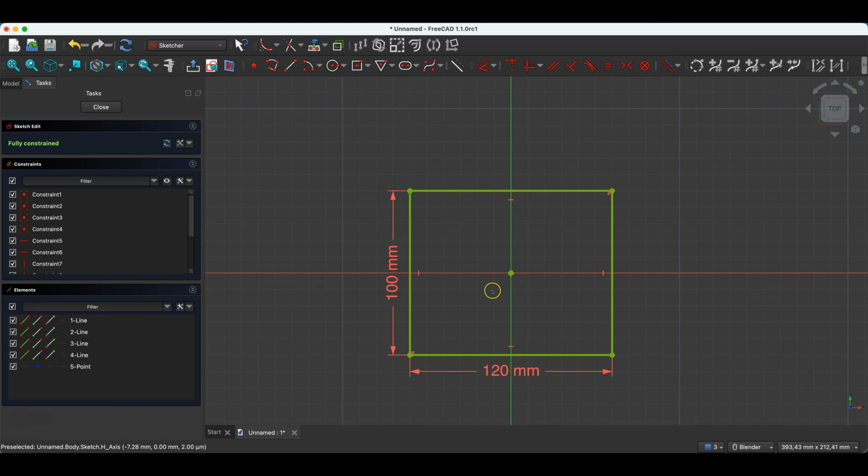In most cases, automatic constraints work well and are very useful, but sometimes situations can arise, especially when there is a lot of geometry close to each other, where we might accidentally apply a constraint we didn't intend. This will of course become more understandable to you if you start creating more complex projects in FreeCAD, but if you would like to disable automatic constraints, you can do it here. Expand these options, and here you have the options for auto constraints and auto remove redundant constraints.